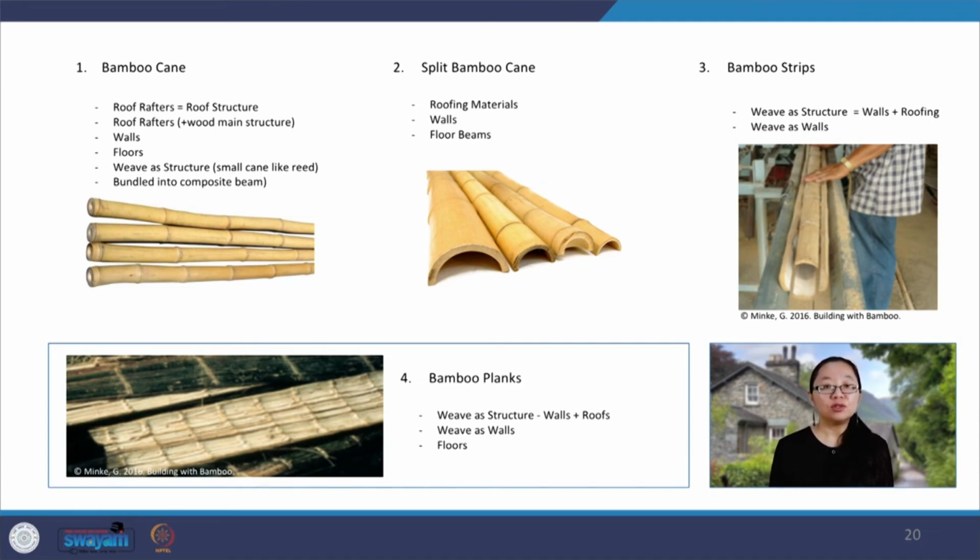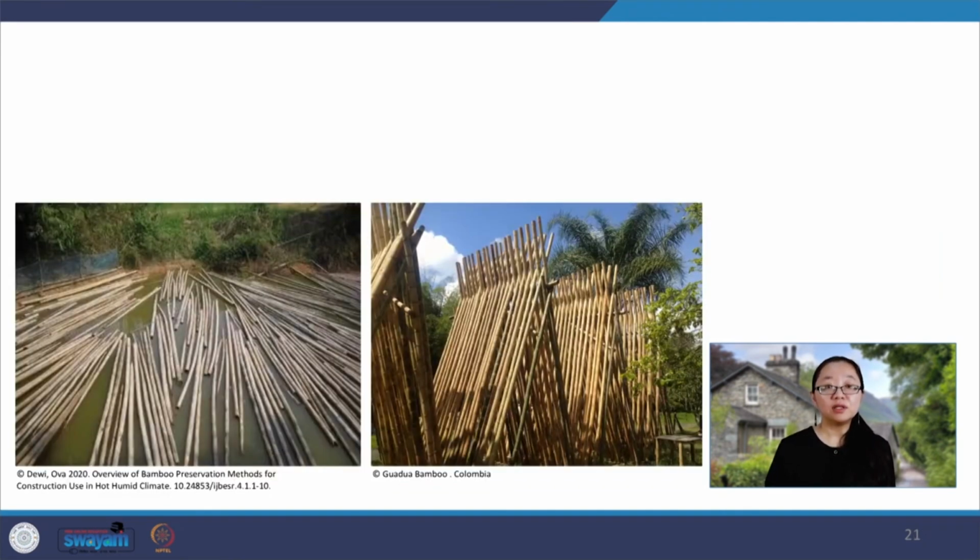Before we continue to look at how bamboo is used today, we need to highlight the drawbacks of using bamboo as a building material and learn the treatments to reduce the impact of those drawbacks. Bamboo is vulnerable to exposure to ultraviolet rays and rain. Accordingly, it requires protection during the handling, execution, and maintenance of the project. Furthermore, bamboo contains a large quantity of starch, which attracts insects. Also, the presence of humidity can cause the appearance of fungus and lichen.